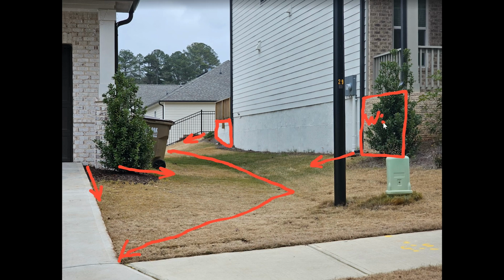But with this, because of the street having some significant slope to it, we have what's called turndowns or subwalls that go into the houses to help step down the grades in between the lots as it goes down the road. So from the finished floor elevation, we measure down to the proposed grade and either determine whether it's going to be a turndown or subwall.